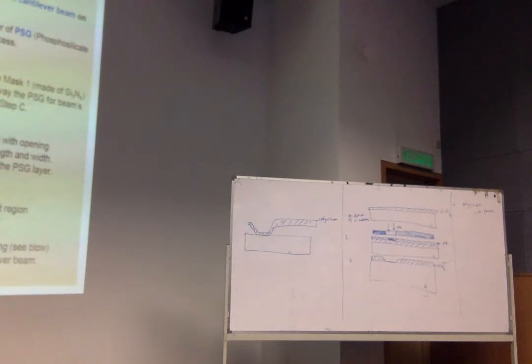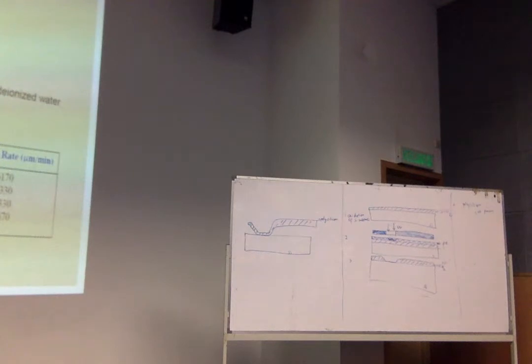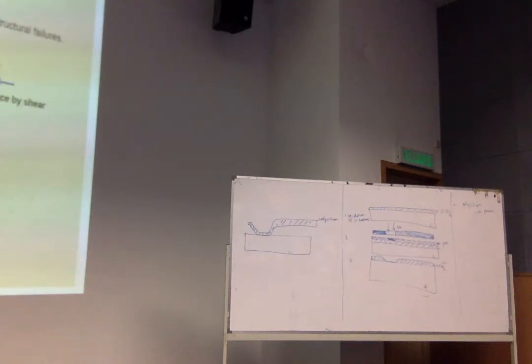Also the oxidation and the CVD process happen at very high temperatures, so we do not know what other things will go through. So there are several problems with surface micromachining. As I mentioned, the commonly used sacrificial layer, again there are some numbers, but silicon dioxide is the one I have here, that's why I showed it as an example. There are certain problems in surface micromachining. Sometimes I have asked this question for 2 marks, 3 marks or 4 marks in examination. What are the possible problems?